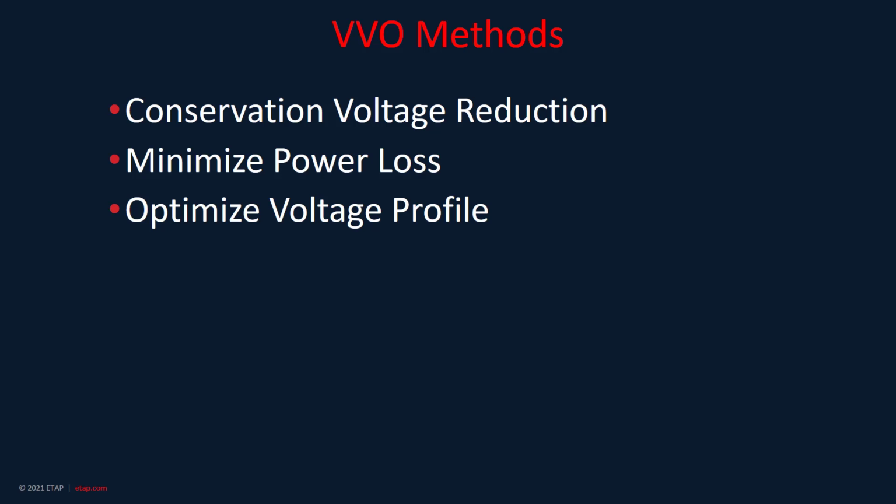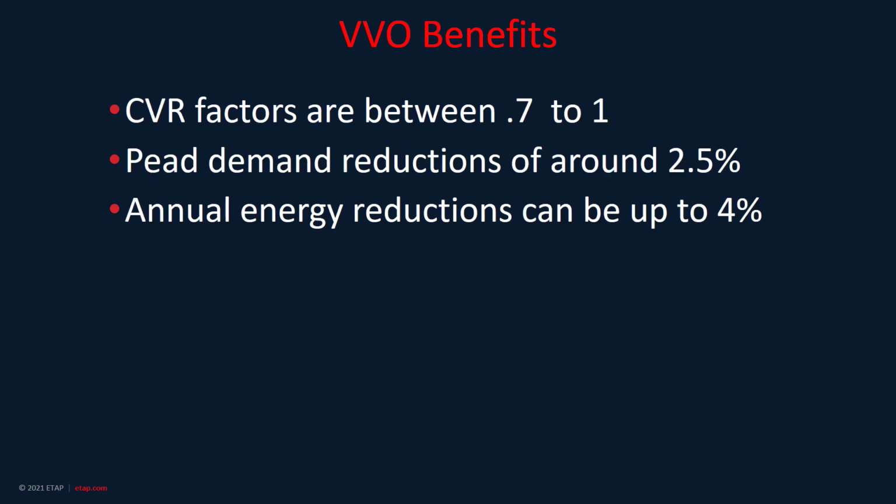Minimize power loss, stay within voltage range while minimizing losses, but fluctuate when load predictability is unknown. Just keep voltage close to normal within voltage swings. The CVR factor of 1 means that for 1% of voltage drop, 1% drop in energy results. A positive CVR factor is desired.